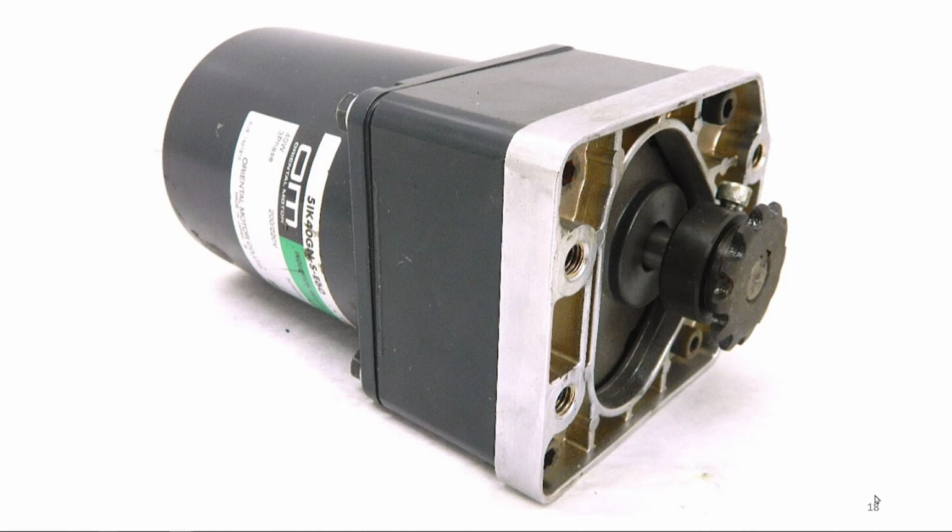It's got a gear reduction unit on it. So that square thing between the motor and the motor mount and sprocket, that is a gear reduction unit. So this is a three-phase motor. Any motor would have done for the picture. You see a sprocket on it. It could have a pulley, but for a conveyor it's probably going to have a sprocket because it's going to have a chain going to a larger sprocket to slow the speed down. So a gear reducer gives you a lower rotation at the sprocket than you have at the shaft or the armature.